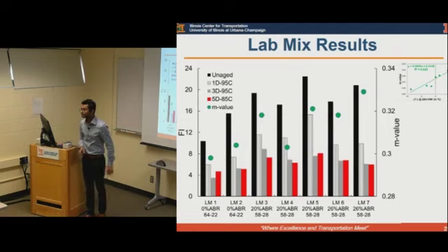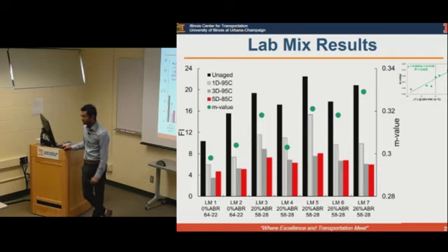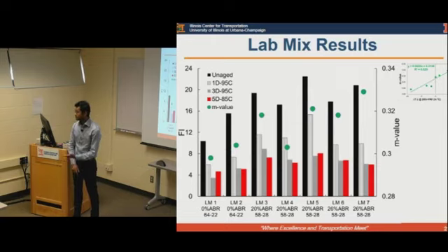Another question. Usually now when we talk about aging, everyone talks about UV. We also talk about the PAV, RTFO, and all of these methods. And then we are trying now with the new machine that you were showing to add moisture and UV together to simulate what's happening in the field. But my question is, how important is it? At the end, if any technique, even if it's very simple, gives me the same chemistry as the aged binder, why does it matter to put in all of these conditions?